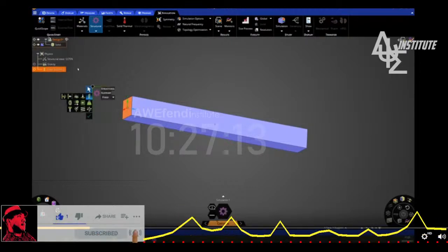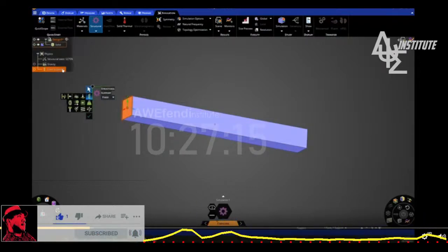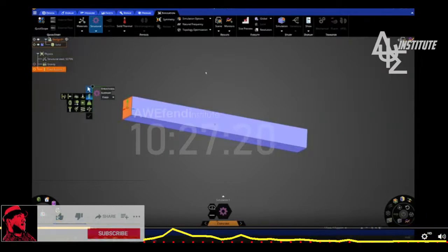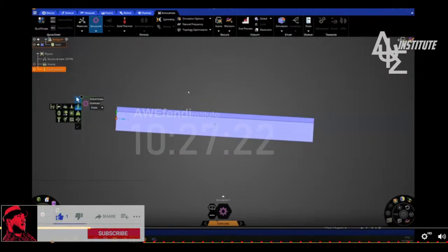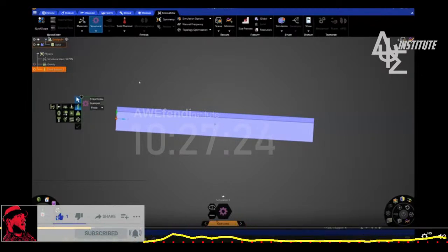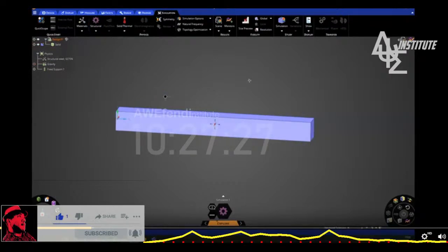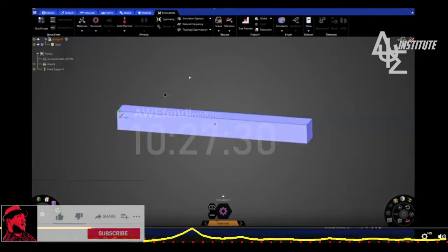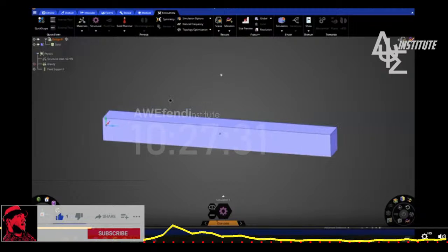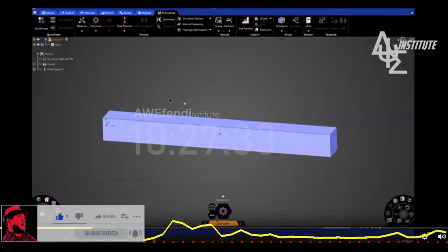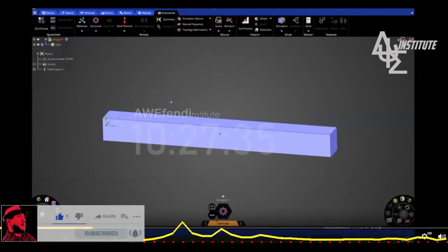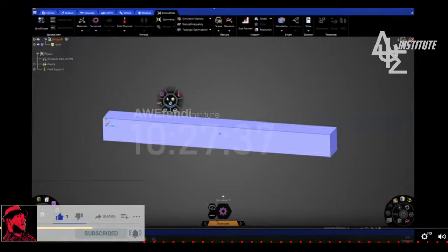As soon as I did that, you can see that now there is a fixed support that has been added to our physics tree. So you know that your boundary condition has been applied. Again, to escape this tool, you click twice. Okay, so then the cool new feature that I mentioned, the halo, you can open it by clicking on the black hexagon over here.